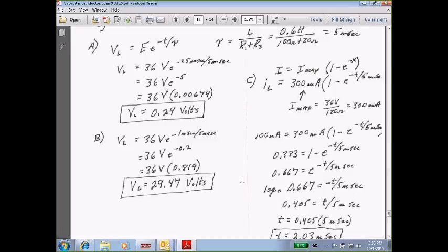Yeah. And of course now, we loop that in with automatic controls, like the idea of power generation. It used to be that your power engineer was constantly monitoring the load at the power generating plant, and constantly adjusting the biasing voltage across the field, your excitation voltage, in order to maintain constant voltage to match the generator to the load. Well, now it's all done automatically. So you don't have a person who's physically doing that anymore, but you've got to have people that understand this is what's actually happening. Sure.